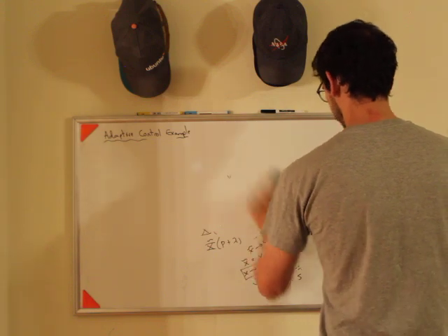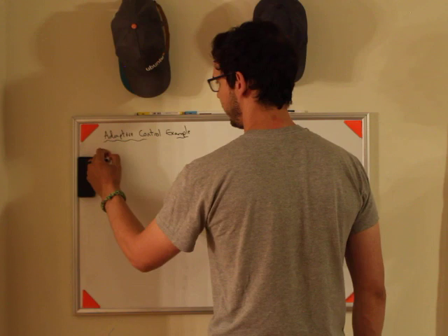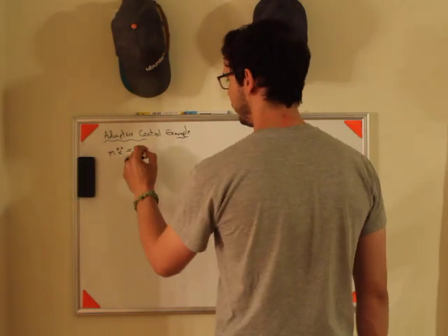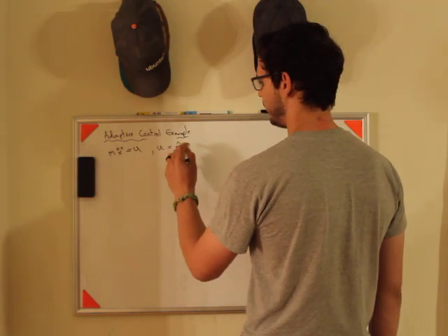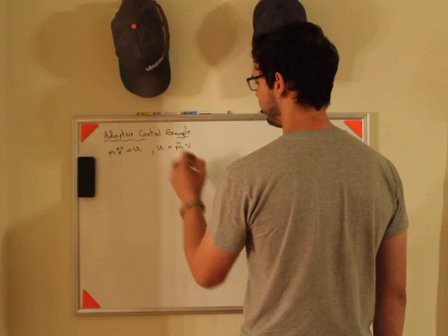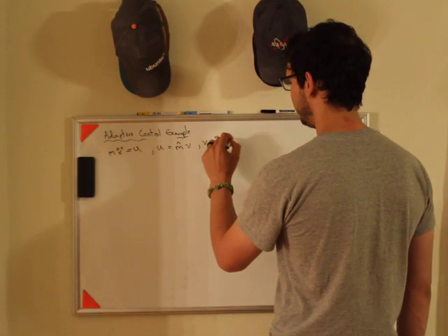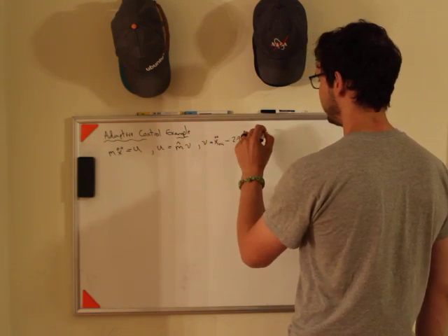All right, so now what we do is we say, okay, my dynamics don't change because that's not something that I can control, but unfortunately, my control variable is going to be m hat times v in this case, where again, v is x model double dot minus 2 lambda x tilde dot minus lambda squared x tilde.